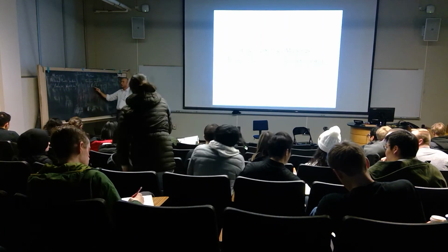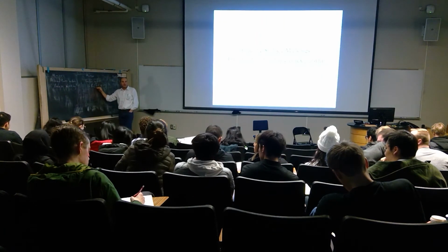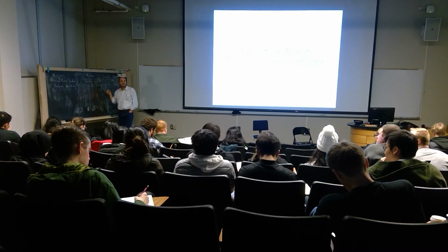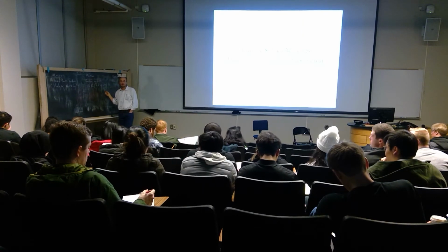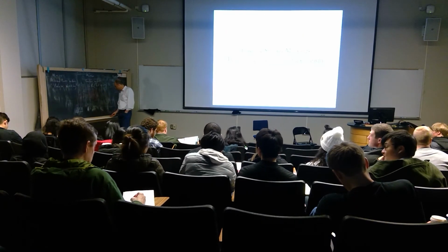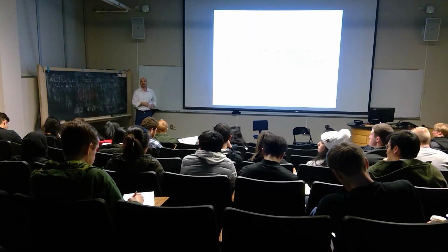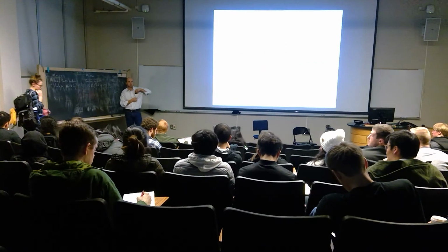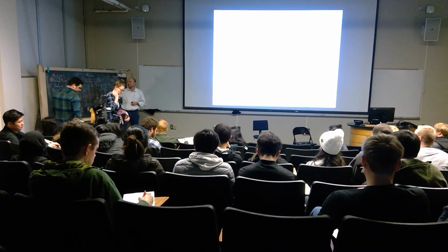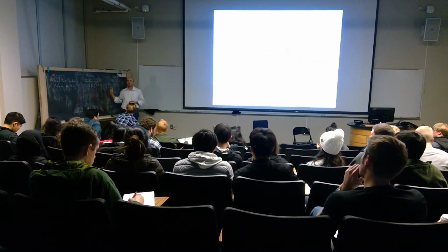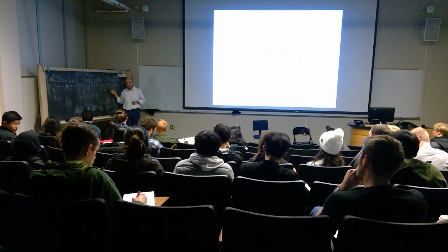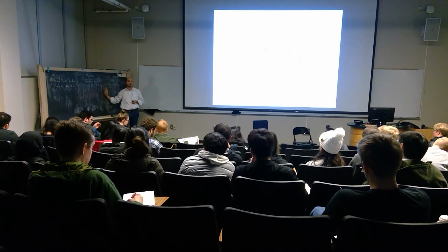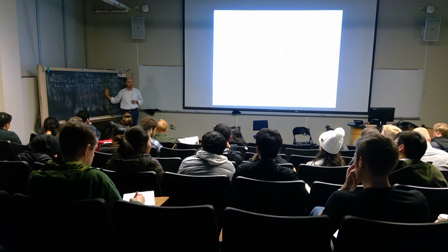It continued through inelastic deformation, but it ends in a brittle failure characteristic because that material cannot fail by development of new surface area through a ductile mechanism. Okay? So, we don't talk about polymers a lot, but you can apply the exact same way of thinking about how the microstructure influences the responses. Okay? So, by definition, that's a ductile failure. But at the end, you will only see the brittle characteristics on the fracture surface because all the ductility was exhausted in that process up to the point in which you developed your surface area.